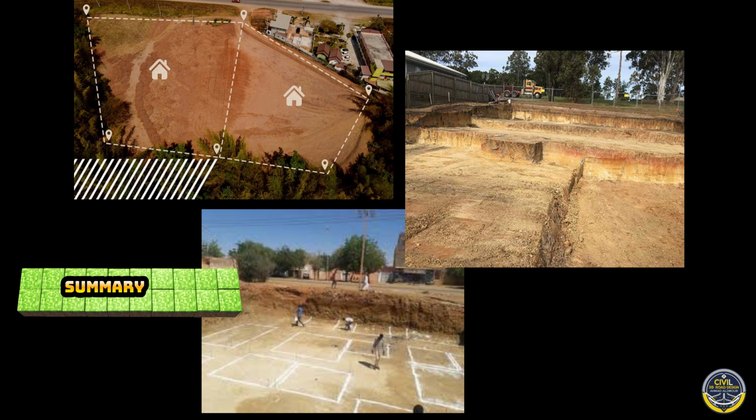Additionally, grading styles and criteria are managed in the Settings tab where you can control how grading is displayed and how it behaves. At this stage, grading should be understood as a system rather than a tool. Grading starts from a footprint, follows a set of criteria, and extends toward a target to create a design surface. It's controlled by feature lines, organized into grading groups, and used to generate surfaces and compute volumes.